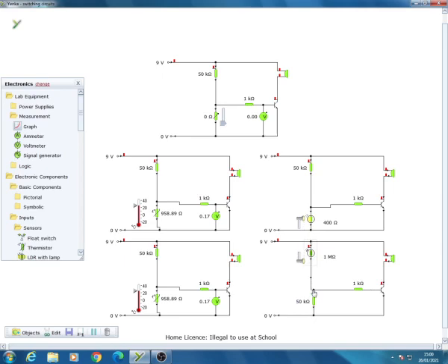Now, we'll do lots of work showing you how to work that out exactly, and showing you what's happening here to change the voltage. But if you remember, it's always the case that, if I put a voltmeter down here, when the voltage across the base of the transistor gets to 0.7, it will switch on. And as this goes up, you can see 0.72, it's gone on, below 0.7, and it switches off.